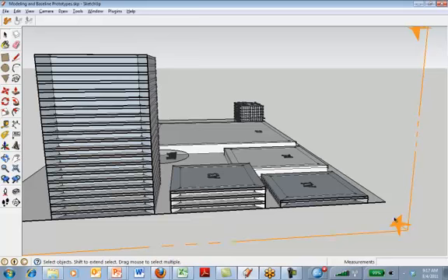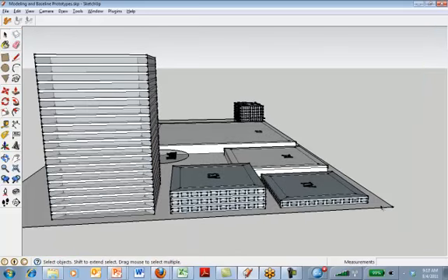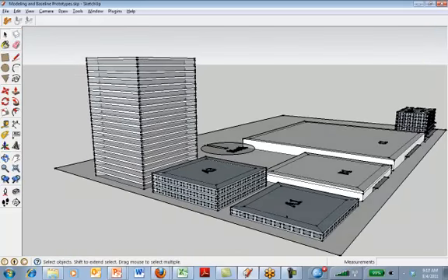And what we want to make sure of is that when you model these buildings, the baseline that's automatically created by the software will be correct. Also, that the fenestration types, insulation levels, equipment types, and efficiencies are all correctly specified according to the baseline modeling rules.